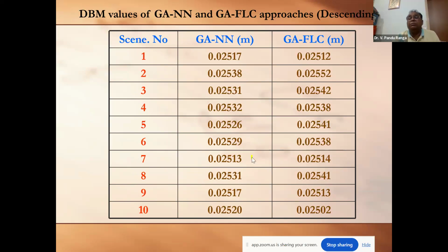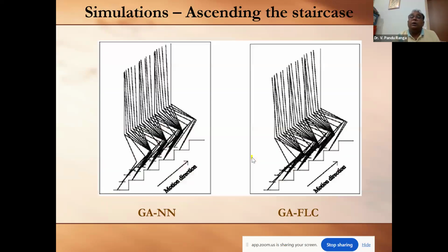So in both the cases we have got gaits that are dynamically balanced. And if you observe the variation earlier, in the analytical approach, the posture of the trunk seemed a little awkward, bending backwards in both ascending and descending. At that time I said this might have happened due to the selection of a wrong trajectory for the swing of the center of mass while determining the trunk motion.